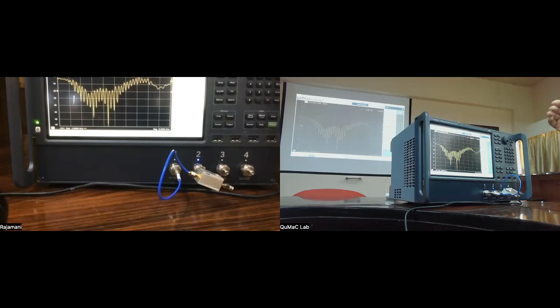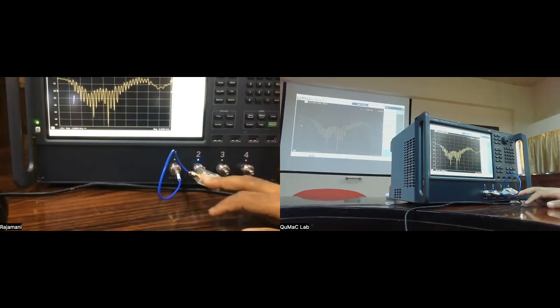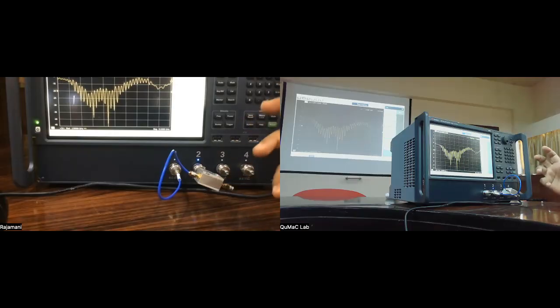So this is what we expect the splitter to be doing, right? This input port should not be reflecting much power. It should be absorbing all the power at the input port. Absorbing meaning here, allowing the signal to go through. It's not dissipating it inside the splitter or anything like that. Okay. So that's what we expect, because this is again a matched 50 ohm device.